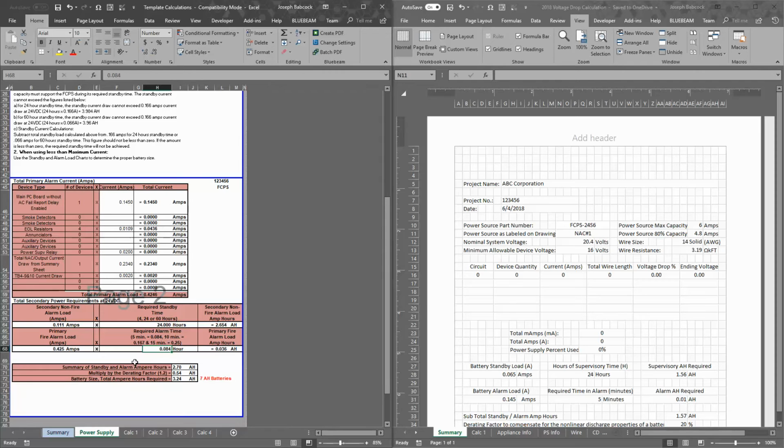inconvenient part, I'll say, is when we come here to change from speaker devices to just horn onlys. We have to refer to this cell on the power supply tab and read this little box. I mean, not difficult, just 5 minutes equals 0.084 hours, 10 minutes is, yeah, etc., etc. So we typically only do the 0.25 or the 0.084, and then that translates right here to our battery requirements.